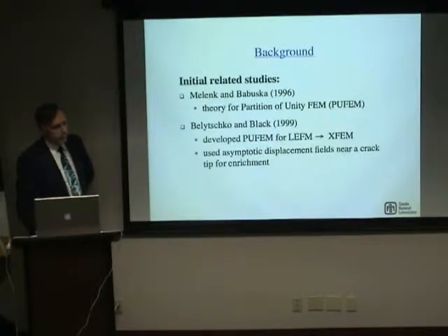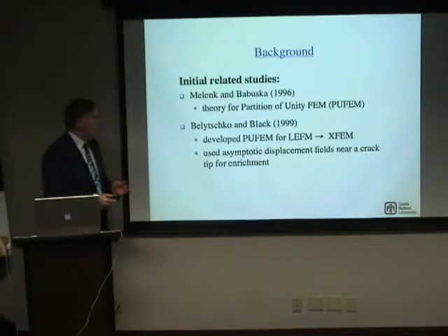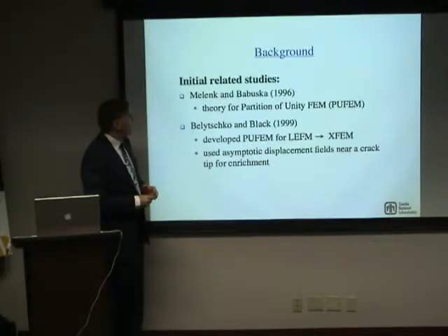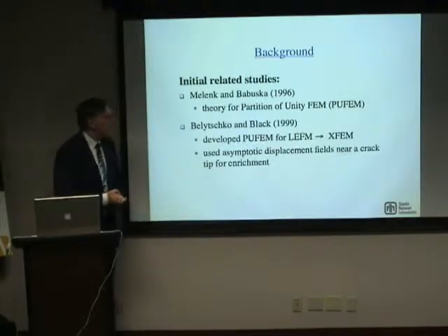Now, in terms of the work that this builds upon, I would say the two papers that are key to all of the XFEM type work is, first of all, Melenk and Babuška's paper in 1996 that provides a theory for partition of unity finite element methods.